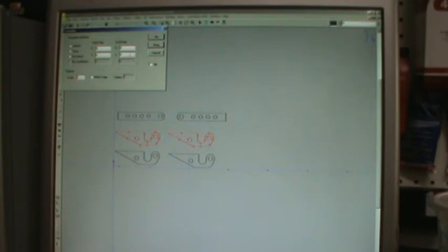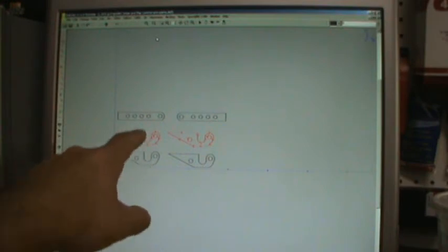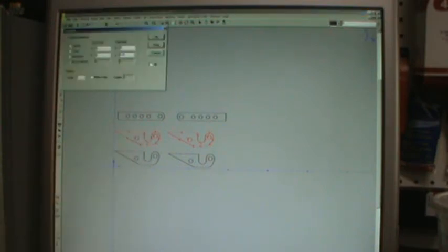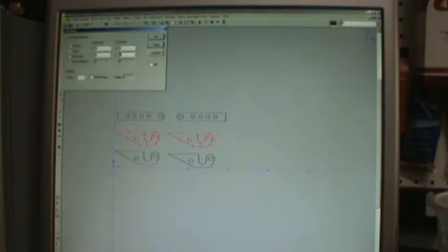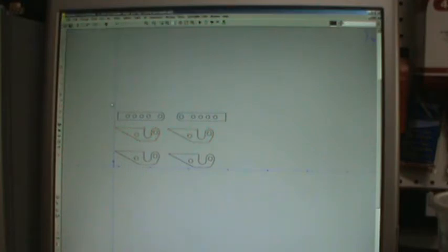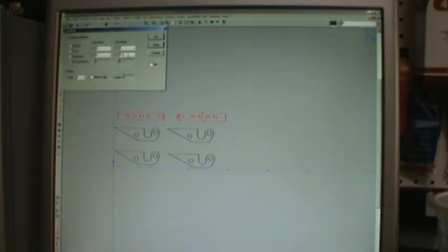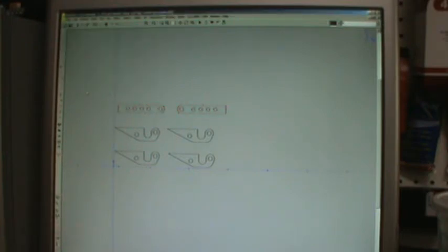What we want to do is just move it in the Y-axis, which you can see up here which direction Y is. I'm going to move it another 10/1000ths of an inch, and you see it just barely moves it a little bit. And just to show you what it does, we'll move it a full inch, see how far it goes up there. We'll undo that, undo the other one, and then we'll just translate that 1/10 of an inch. And then this one up here, we'll also translate that one. We'll do a full 3/16 of an inch. So there we go.